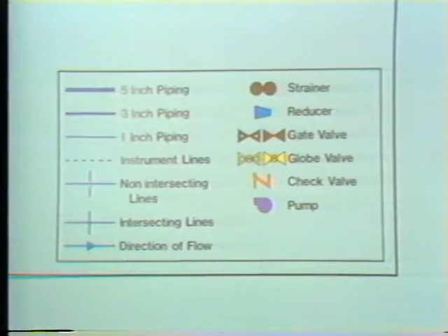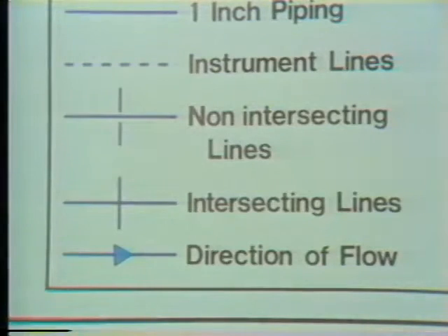Remember that this is the legend for this print only, and that you must use the legend that goes with a particular print. One of the important points to observe in a legend is the way in which the pipes are shown to join or to cross over each other without joining. In this method, the non-joining line stops on one side and starts on the other, never touching the line that it does not join. There are several other methods of doing this. This is just one. Your text shows some of the others.